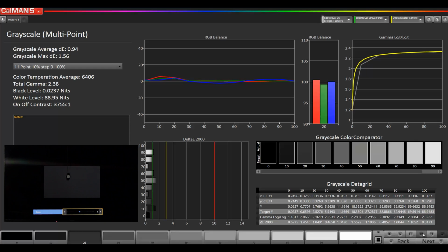And that's why colorimeters are so good at measuring black levels, because they usually have larger sensors and there's fewer of them with the larger lens, whereas a spectroradiometer has a smaller opening, tons of sensors, but the light's being broken out across the visible light spectrum, and a tiny little bit of light is hitting each sensor, so this is automatically adapting.